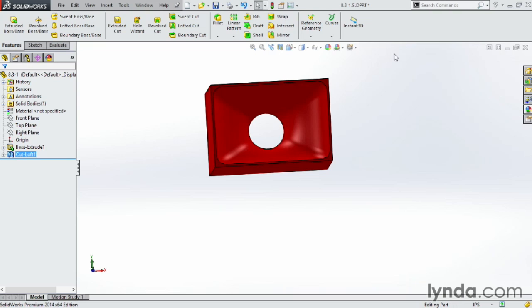And again, you can play with those direction vectors and those normal to profile values to get any shape you really want. Keep in mind, when you do change these values or you make lofted cuts, these are freeform surfaces now. So they're very difficult to define on a drawing or to relay to manufacturing. It's mostly going to be something we'd use to do like some type of a molding process or a casting process.